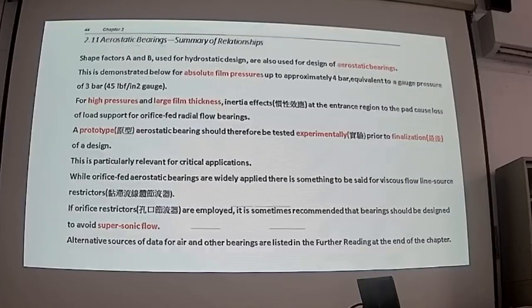For most aerostatic bearings in practical application, usually they use the orifice restrictor. Most of the case, 所以大部分的气压轴承在实际应用上都是使用小孔节流器或空口节流器。Only very few use the capillary restrictor. In most of the case, the majority, I would say more than 80 to 90%, they are using the orifice restrictor.